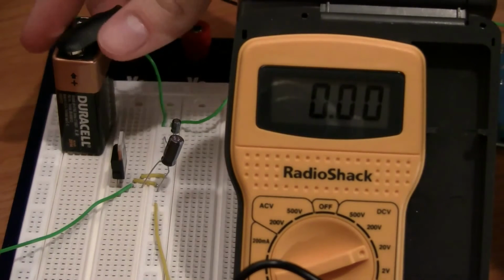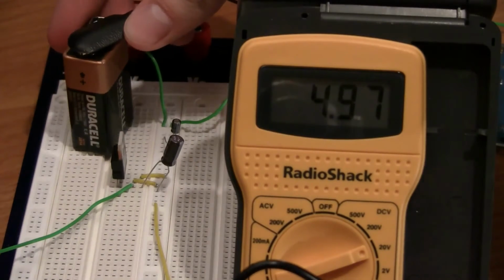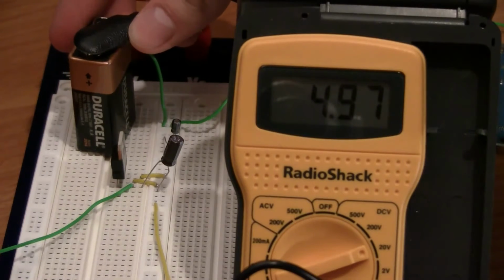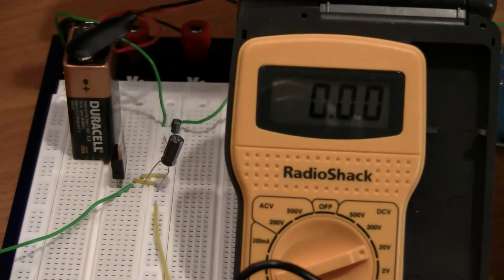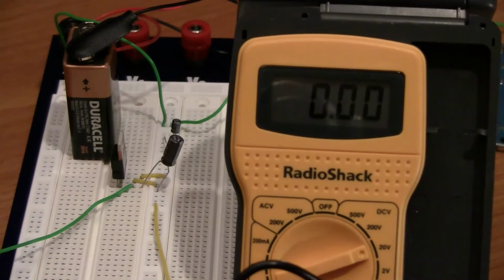If we hook up the battery, we can see that the voltage goes straight up to 5 volts, just like we want it to. And if we disconnect, it goes right back down to 0. Regardless of the voltage level of this battery, as long as it's within the acceptable range designated by the data sheet, we'll always get 5 volts out of here, which will be perfect for powering a lot of projects. Note that as this battery discharged, we'd be getting a different voltage if we were using a voltage divider, because it would change the input voltage and therefore the output voltage would change accordingly.